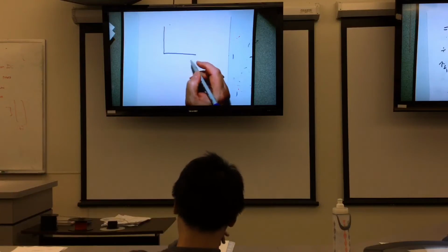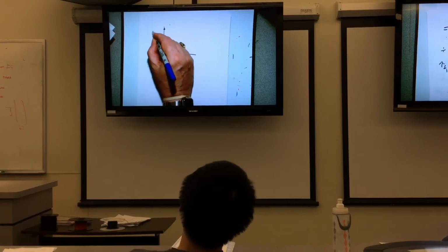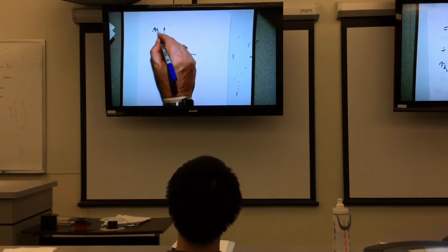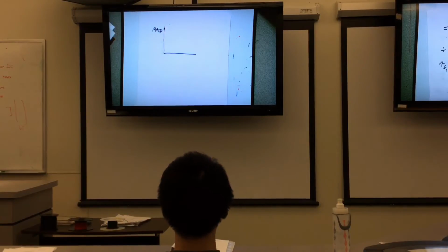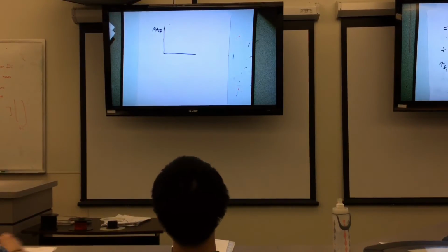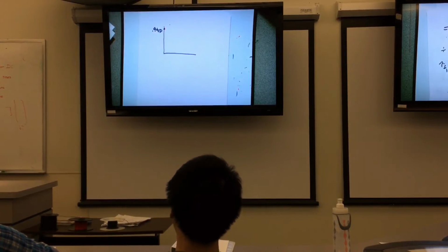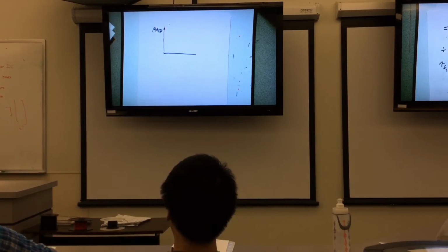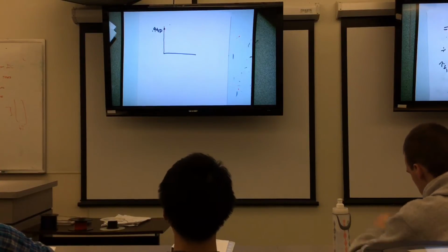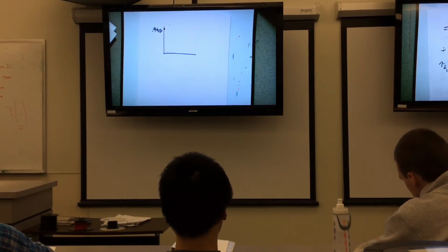What we have at this point is we started out at 0.9 VDD, which is 90%. We're doing a 10%, 90% study, actually, when it's all said and done. But we're assuming the input is an absolute perfect step instead of VDD. It's just an artificial thing to make the math simple.